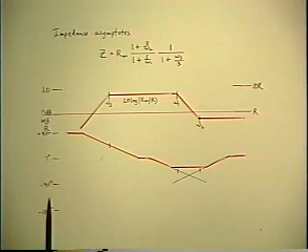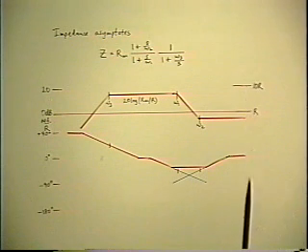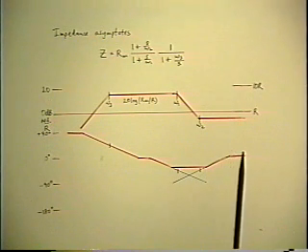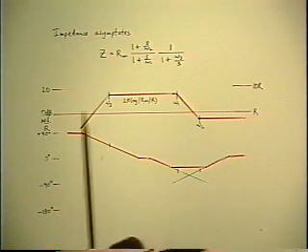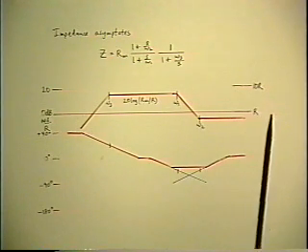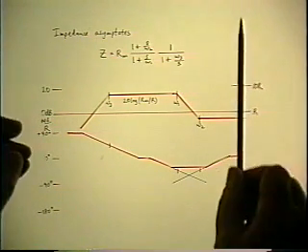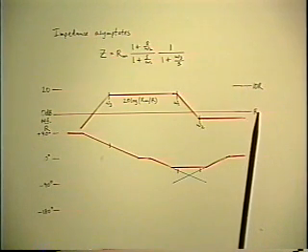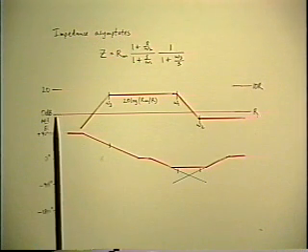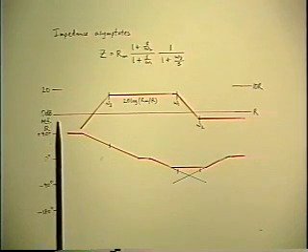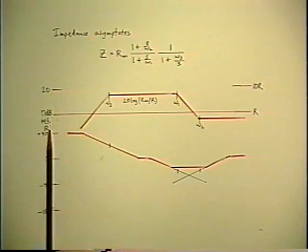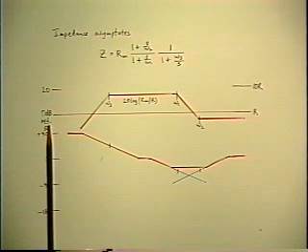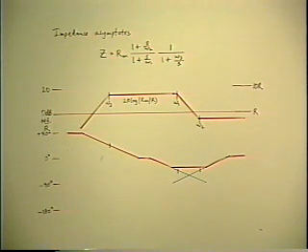So you can have a dB scale on the left, or you can have a true logarithmic scale of resistance on the right, and the reference resistance that you've chosen sets the 0 dB level. And you can simply scale that up and down as you wish by choosing different values of reference resistance. Now, the only catch to this is when you label the dB axis, you ought to label also what the reference resistance is. Otherwise, you don't know what 0 dB corresponds to.